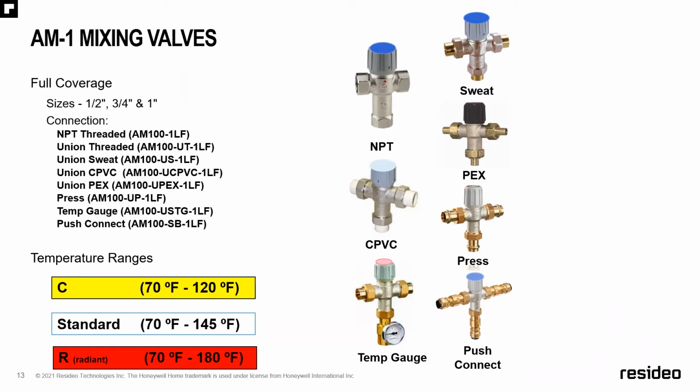The sizes run from 1/2 inch all the way up to 1 inch, and we have connection ends from NPT all the way up to push connect. Sometimes I get people asking me about the NPT not having a check valve. Well, if you do need a check valve, which many applications do require, we have an additional tailpiece that you can thread onto the NPT mixing valve that has a check. So if you have any questions about that, reach out to your local distributor or your territory manager.